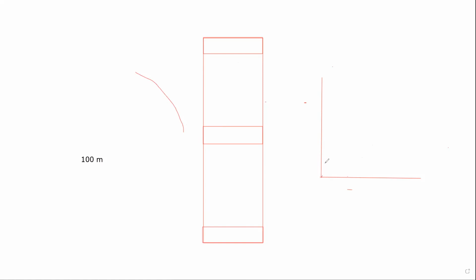According to that, if your structure's stress strain curve is like this, there will be hinges in the structure, right? Like see, here we find some of the hinges in the structure. To avoid that deflection in the structure, we will provide some kind of belt. This belt may be with a shear wall, or RCC wall, or maybe with steel sections. If you are doing it in steel, we can provide steel plates, right? So these are some of the advanced things that we have to study. Got it? So you are now studying the course, so basically what will be the conclusion for our building type?